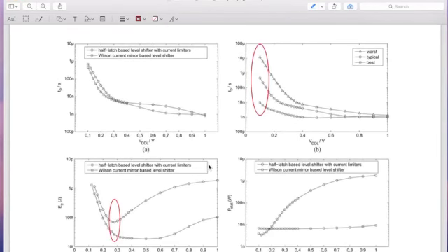Okay, so one way of addressing that is basically to use different voltages. You don't have static voltage scaling, but you have to allow for what is called adaptive voltage scaling. That means the voltage used really depends on the process condition. Right? That is what adaptive voltage scaling is, and it essentially will have a way by which you sense what the process condition is and adjust the voltage. For example, if you are on this curve, you use a higher voltage. If I want this delay, then I use a voltage which is higher, so that I still maintain that delay.